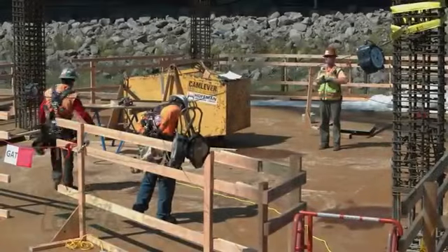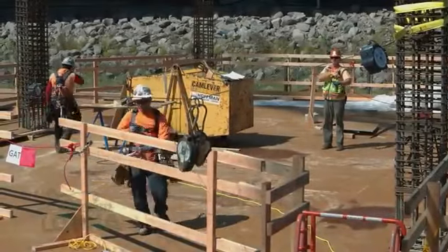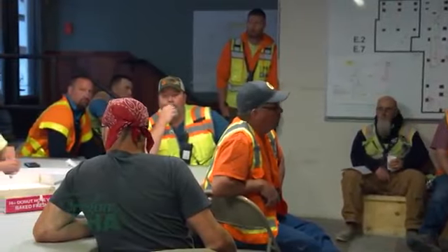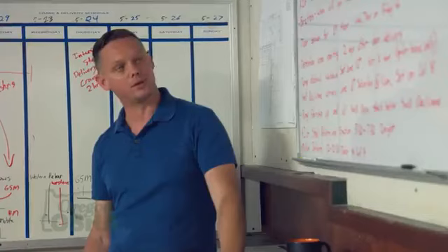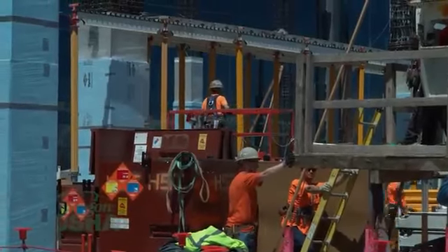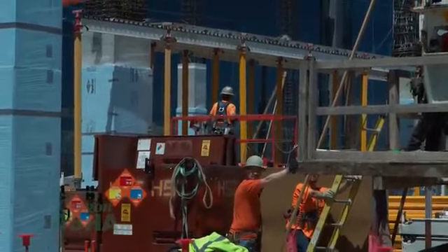I usually identify high-risk activities, and then at that time I work through the plan with the team that's going to be doing it, or at least the foreman and superintendent that's going to be performing that work. I like to have them tell me the plan, and then I also know how that work's going to go, and then we identify certain areas where we can eliminate risk, and then we try to have a plan before we even get started to eliminate that. Again, when you have a plan that you can work around and it lets the worker do their work without trying to figure out how to get around handrails and tie-off systems, something that's easy for the worker to use, that's going to be the safest way to do it.